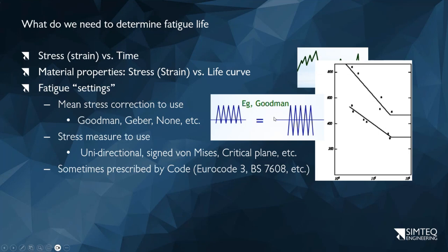And that then effectively determines what the fatigue life for the component should be. So the minimum of any of the directions is your fatigue life then.